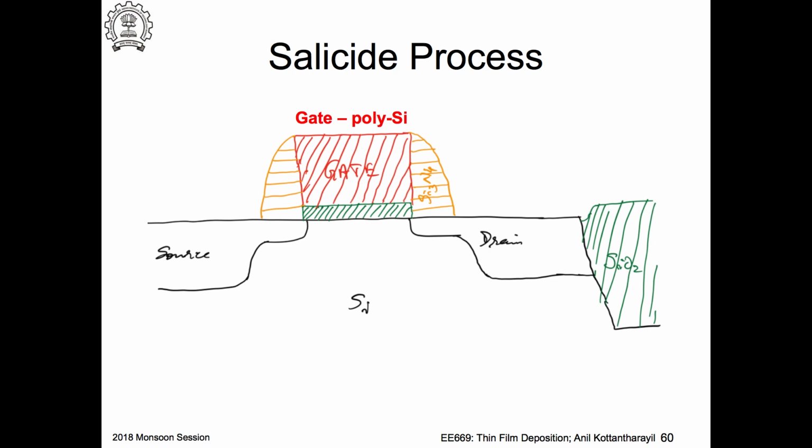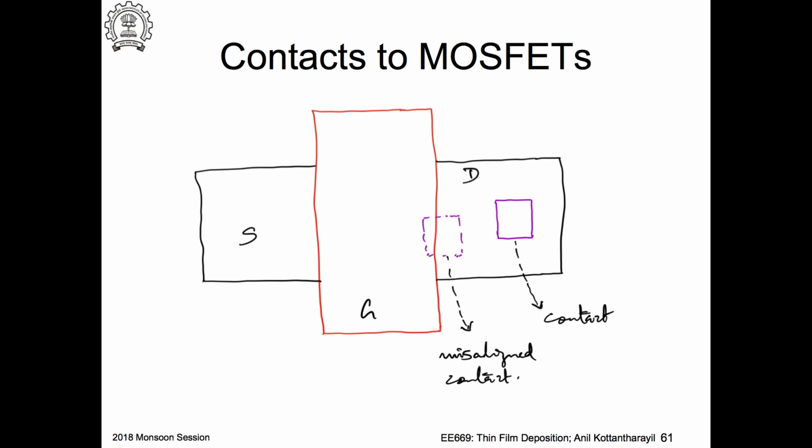So what you're trying to do is retain this metal only where you want it. Yeah, we want these strips of metal, right? But if I do photolithography and if I do the lift off, again that depends on the photolithography, right? There's something called alignment. Yeah. So what this means, so when you design the layout of circuits on an IC, right, which is part of VLSI design, okay. So now I want to make the contact. What is my problem if I do lithography?